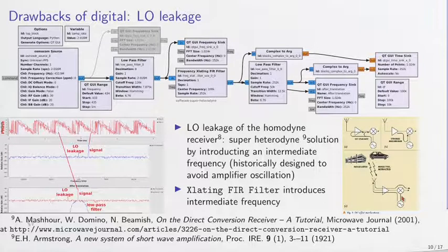But as will be seen in the next slide, if we want to analyze close to 0 Hertz, close to carrier spectral characteristics, amplitude or phase, then the local oscillator leakage will become an issue. How do we demonstrate this local oscillator leakage? Well, if we take an SDR DVB-T receiver and look close to 0 Hertz, so we significantly decimate.